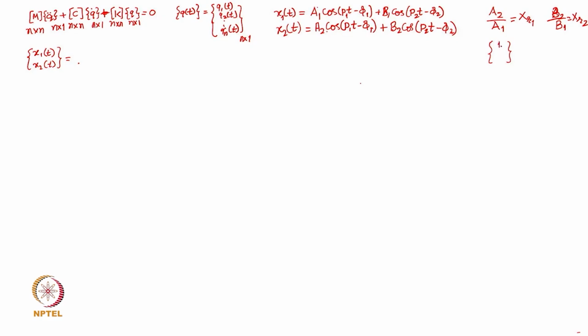So, if we now see this in one specific case of a 2 mass system where the degrees of freedom were 2, and their numeric values were such that the mode shape was 1 1, then that actually means that a2 by a1 was 1 for the p1 mode, and then b2 upon b1 for the second natural frequency was minus 1. So, this mode shape was 1 minus 1. Why? Because b2 was equal to minus b1. So, if b1 is 1, then b2 is minus 1. That's how it happens. So, this 1 is nothing but your XR1 and this minus 1 is your XR2.